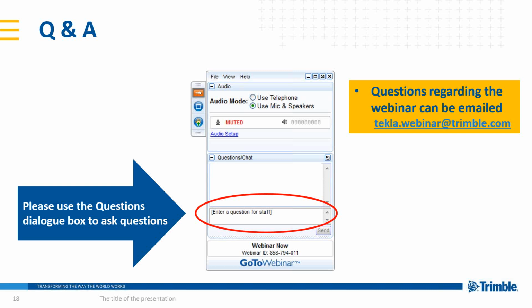Okay, thank you. And the next question is also regarding the Unitechnik file. Does all information from the model go to the Unitechnik file, or can we exclude, for example, some embeds or rebars? Yes, we can exclude, for example, embeds or rebars or meshes, and there are quite many different options to choose what and how we want to export these Unitechnik files. Although there are many settings or options, we don't have to set them every time. We can just use the pre-saved settings.